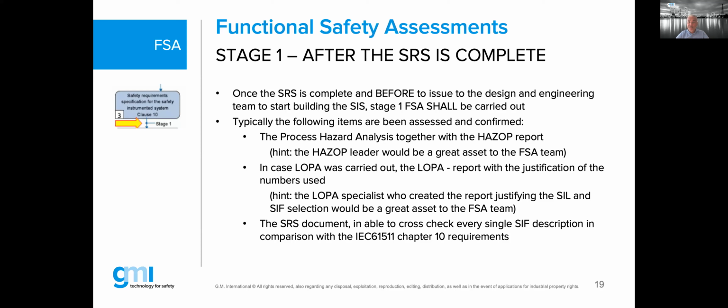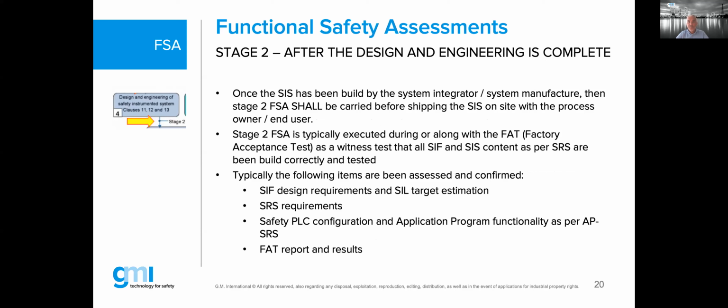And only then I can start to make a judgment on the description of the required additional risk reduction, if that is adequate, yes or no. Of course, the SRS will be checked against the bullet list from the IEC 61511, and we have 29 items per safety loop. We do have an SRS webinar also available, so if you go to the YouTube channel, you may see some, or you may inquire about one of the SIL manuals or SIS manuals from GMI.